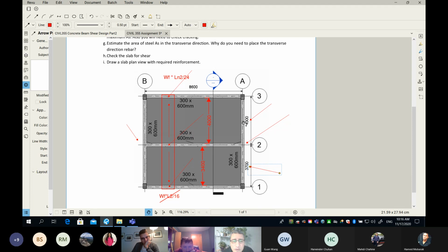And some of you showed all the rebars. Look at this, they showed all the rebar. I'm not asking you to show bar by bar all the rebar, otherwise it is too heavy. That is what I showed you in my Revit model, where I generated all the rebar. However, for a structural drawing, we do not show all the rebar.